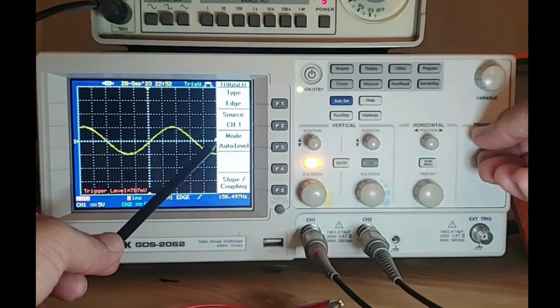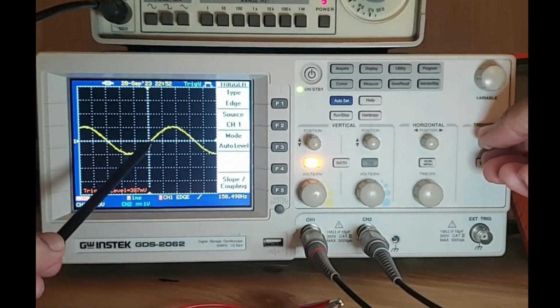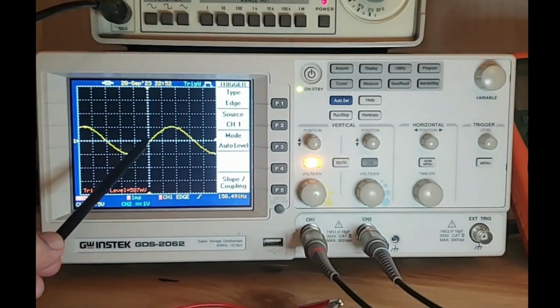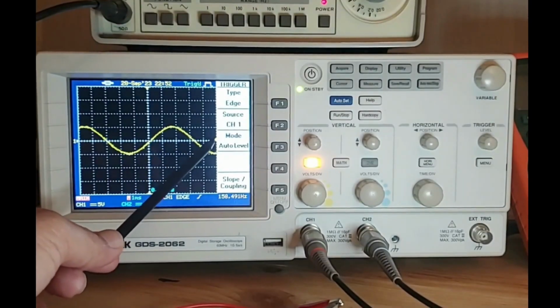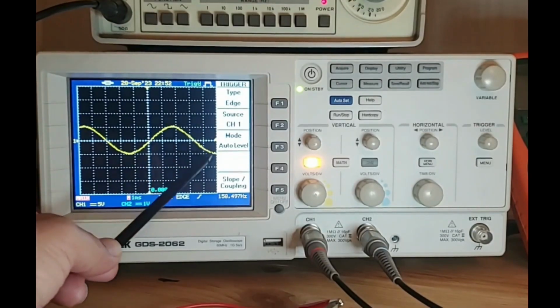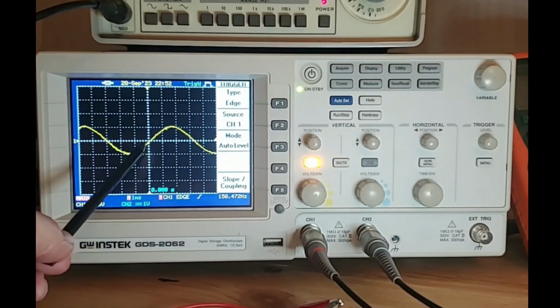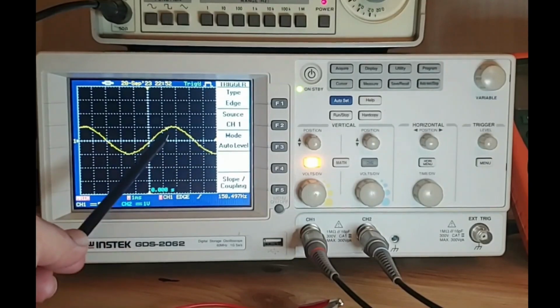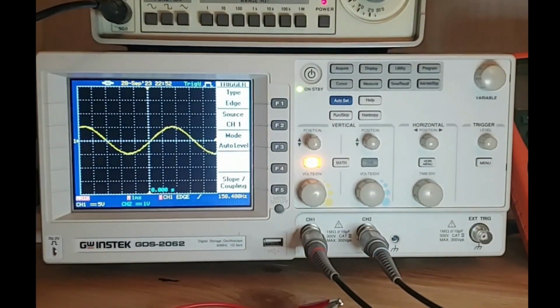And if I bring this arrow all the way to the 0 point, then you see this waveform will start at 0. Okay, so this is the trigger level, which actually tells the waveform when to start plotting. So it will start plotting from the center, half here, and then half here. And then the oscilloscope will wait for the next trigger to happen, and then it will start plotting again. So the next trace will fall on the previous trace, and we will be able to see a stationary waveform.